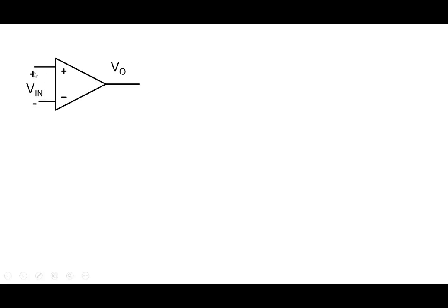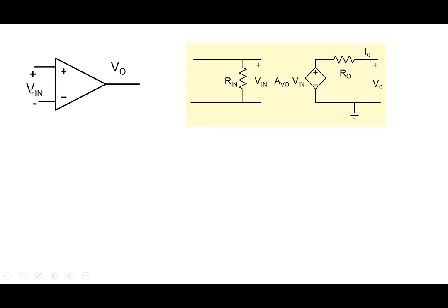Basically, if I look at it from the outside, external to the amplifier, how does this amplifier really behave? One way in which we can describe this amplifier is by this equivalent circuit here. If you look at the amplifier between these two nodes, whatever is inside we are not bothered, but the whole thing can be modeled. Now the word is important.